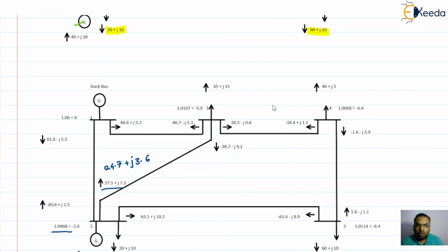So we can analyze here how things will be when there is a line outage. What we have to check is that definitely overloading will be there, voltages on buses are changing, and line flows are changing.